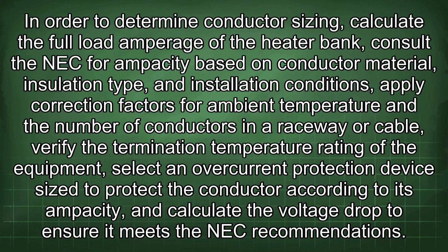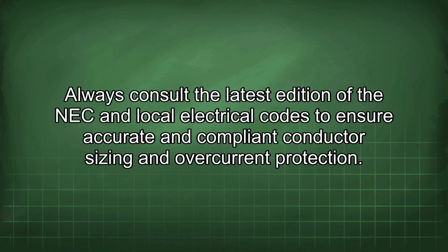In order to determine conductor size and calculate the full load amperage of the heater bank, consult the NEC for ampacity based on conductor material, insulation type, and installation conditions. Apply correction factors for ambient temperature and the number of conductors in a raceway or cable. Verify the termination temperature rating of the equipment. Select an overcurrent protection device size to protect the conductor according to its ampacity, and calculate the voltage drop to ensure it meets the NEC recommendations. Always consult the latest edition of the NEC and local electrical codes to ensure accurate and compliant conductor sizing and overcurrent protection.